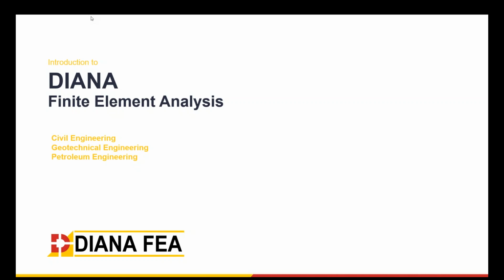It will consist of a presentation to give you an overview of the capability of the Diana software, followed by a short live demo where we highlight some of the features of Diana. And today we will focus on one of the new outputs that we have for the distributed moment, which is based on the Wood and Armer method from the Eurocode 2.